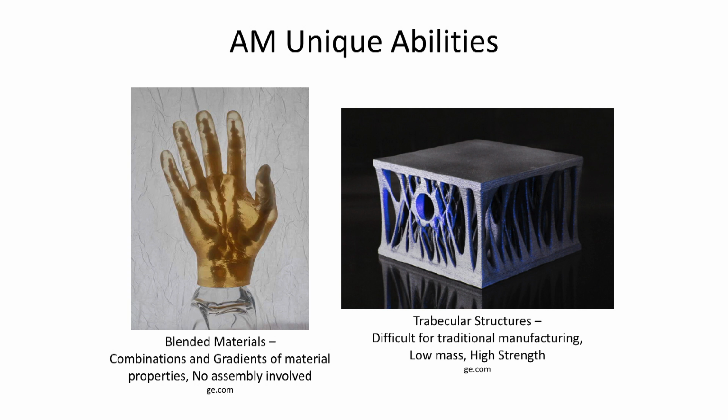We're going to take a look at a few examples of that, but the most important things to keep in mind are that we can leave internal spaces where we decide to do so, especially with fused deposition modeling. With other methods, we may trap our excess material or uncured material like resin or powder, in the case of powder metal printing, inside of those empty spaces, but with fused deposition modeling, we're only trapping air inside.